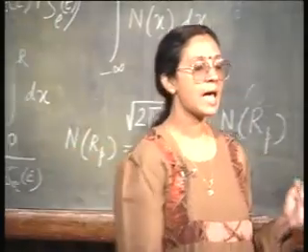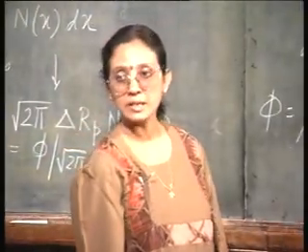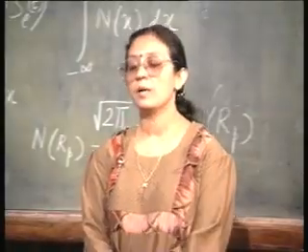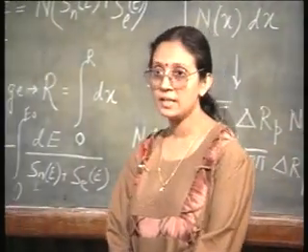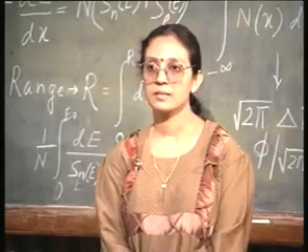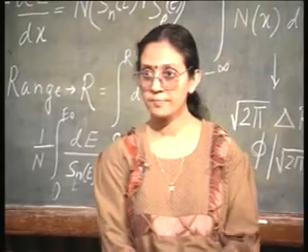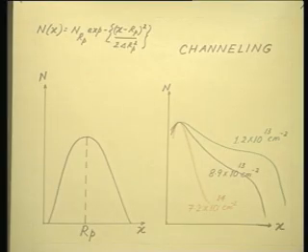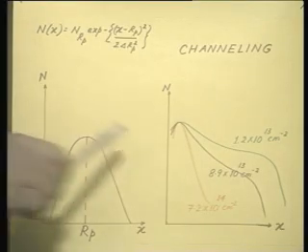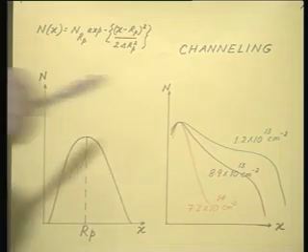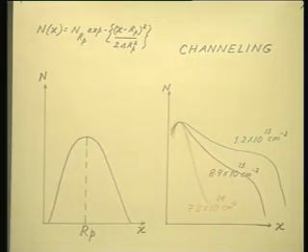That is, as the dose increases, the amount of channeling becomes lesser and still lesser, right. See, look at the orange curve. It resembles the Gaussian function more accurately than the green curve, which is going much deeper into the semiconductor.